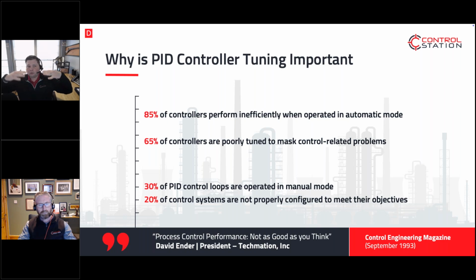You've got interacting controllers, temperature zones in your ovens, and they're all tuned fast, and they're sitting there fighting each other, and so operators drop them into manual, which contributes to that 30%. In fact, we've done audits and analysis of some of our clients, and we're still seeing somewhere between the 20 to 30% range of control loops in manual at most facilities. I would say the average today is still around that 20 to 30%, and the target you should be hitting towards is 95%.